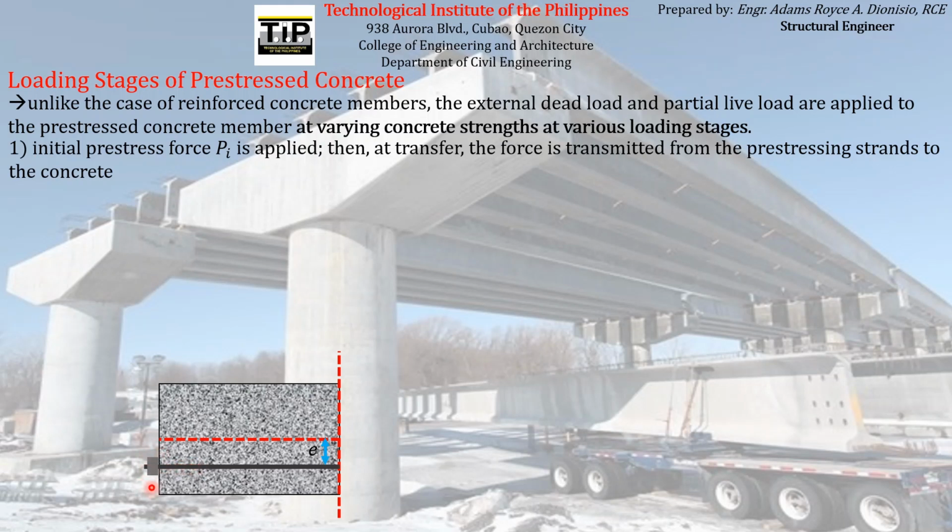After the reinforcement is cut, the tensile force imparted by the hydraulic jack will be experienced by the prestressing reinforcement all throughout its length. Thereby it experiences a tensile force P, and usually that magnitude of tensile force P is what we call P sub I at transfer stage.